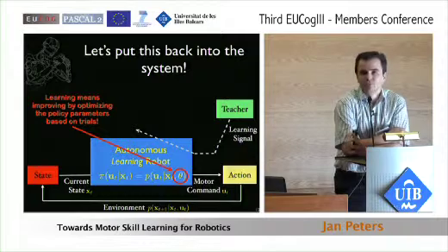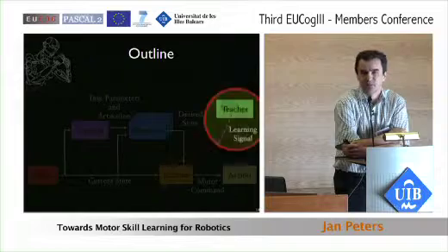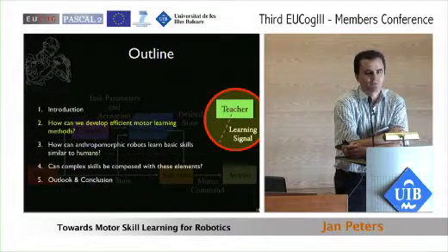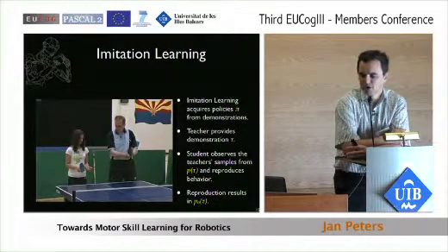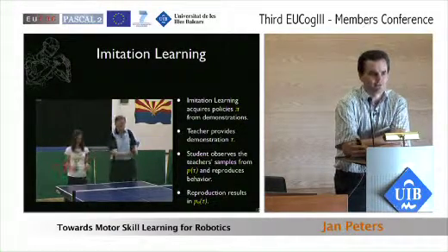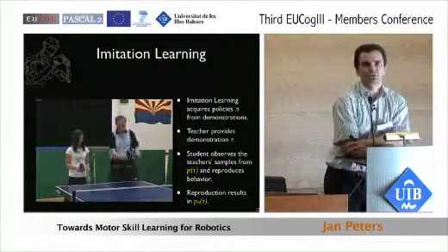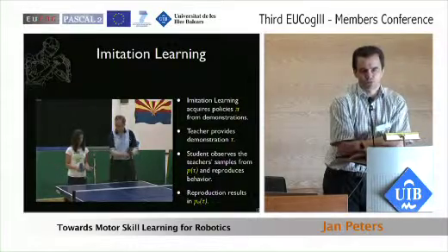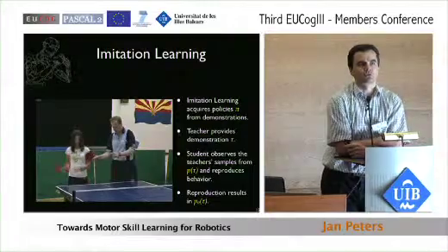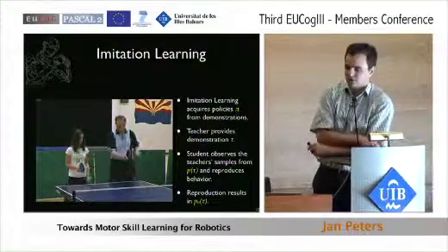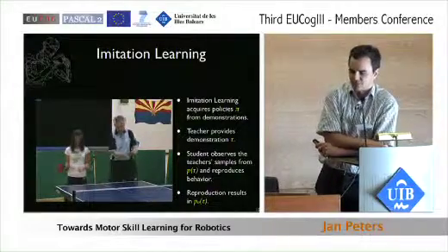And for that, the first thing which we need is imitation learning, reproducing what the teacher does. And this, from a learning perspective, is a very well-posed problem, because what you want to acquire is quite clearly a policy, and you have data, since you have the data of your teacher who provides the demonstration, and you can use this data since you empirically right away have a distribution over such trajectories, and all you want to do is reproduce this distribution using the parameterized distribution from a couple of slides ago.